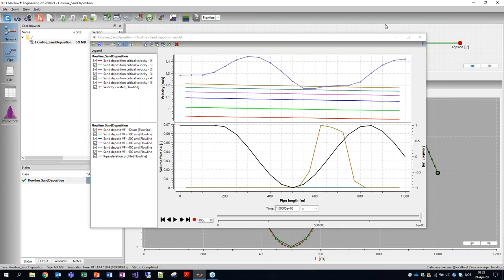For water accumulation, how is the viscosity of the water accounted for? For example, water plus MEG. Yeah, this is not really a part of these models, I think. I'm not sure it affects either the Oskarsson and Turian or the Danielson model, but I would have to check the exact details of how they predict this critical velocity. Okay, so I'll say that we'll check. We don't believe it's part of them. That's not a parameter.